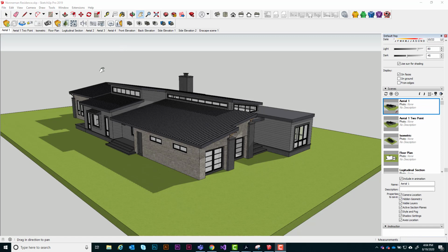All right, so starting off here with this view of this house, this is a 3-point perspective view. So we can see that lines are fading out here on the horizon to the left, to the right, and then also all the vertical lines, although it may not really look like it, they're all converging at a point way down here at the bottom.